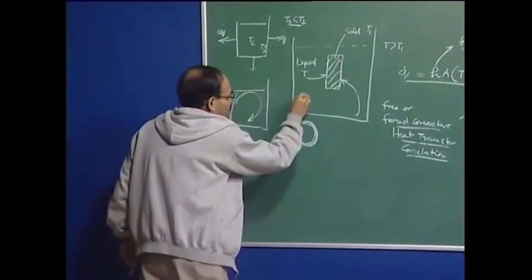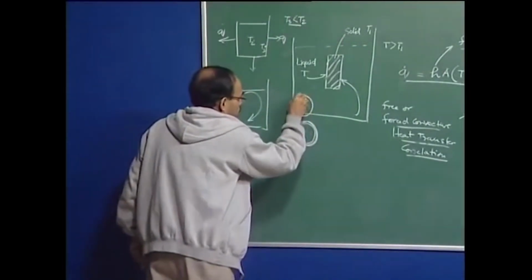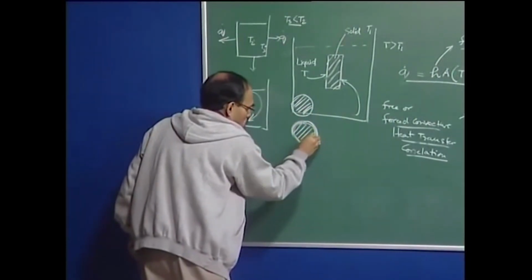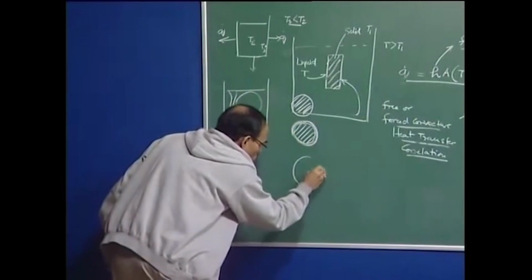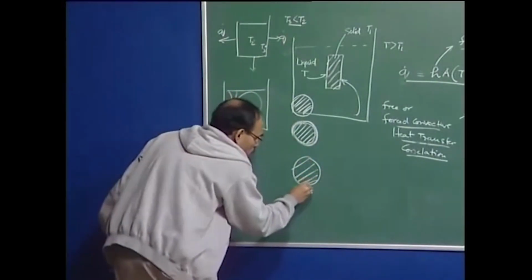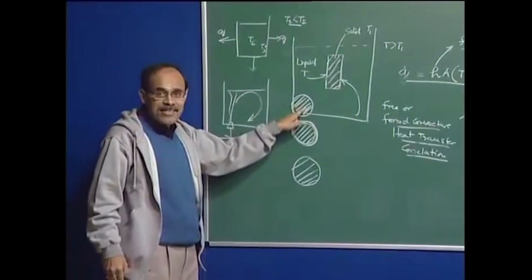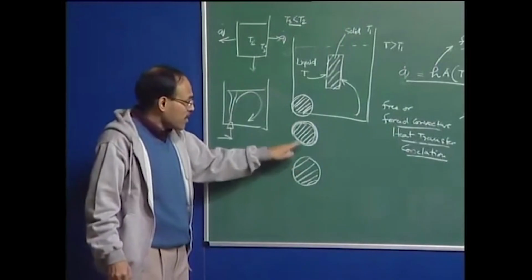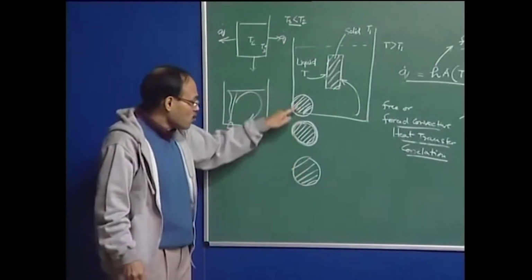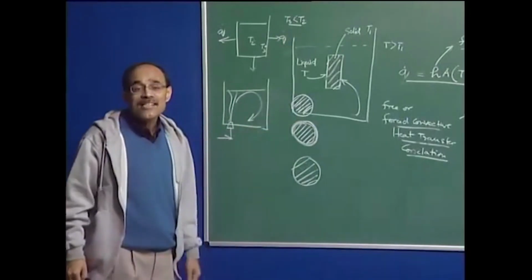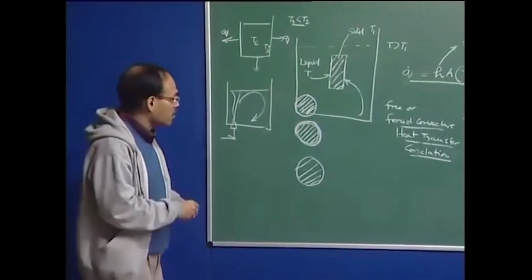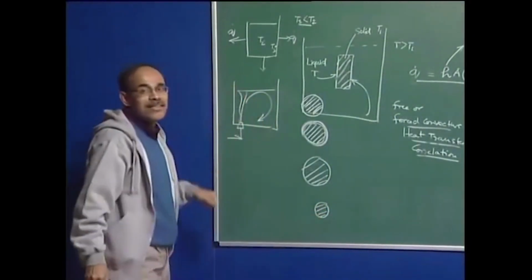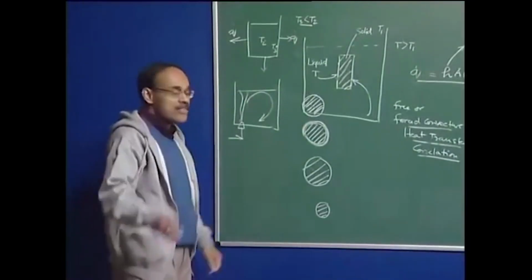So, it goes like this. This is a solid. The next stage is you have formed the crust, and the third stage is maybe again the solid is exposed. So, this is the initial radius, the radius has increased, the radius has decreased, the original radius. So, here and here the radii are the same, and this duration from here to here essentially tells us about the shell growth and shell melt back period, and then finally the size decreases, and eventually the object melts and vanishes into the system.